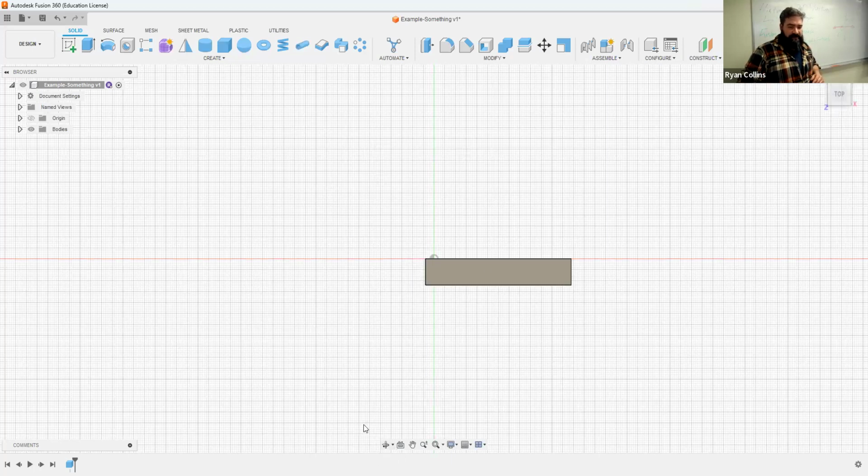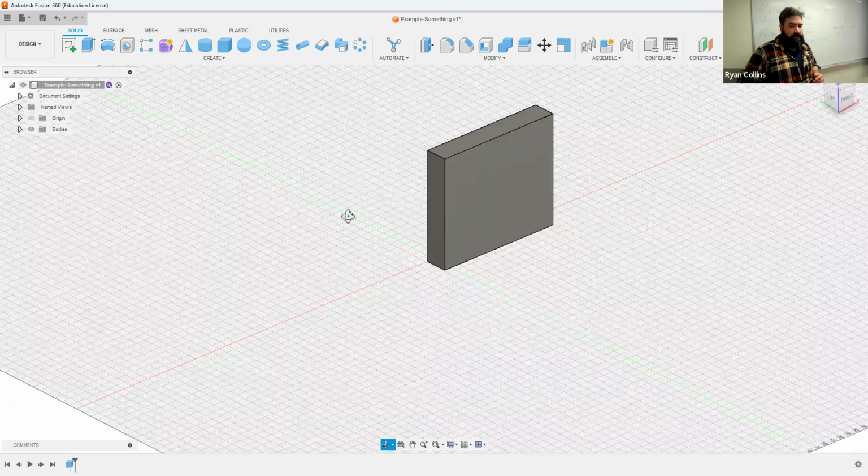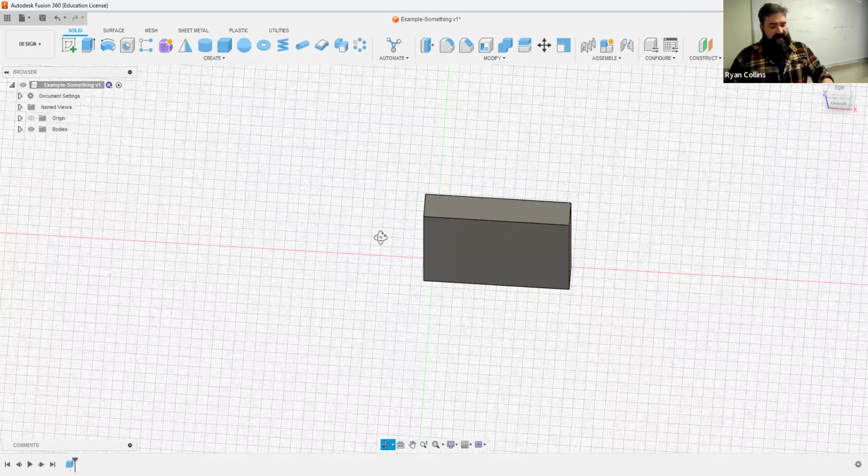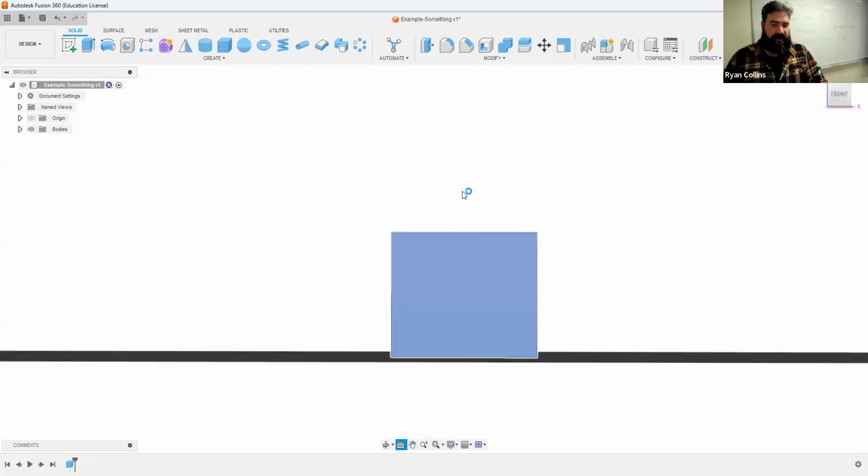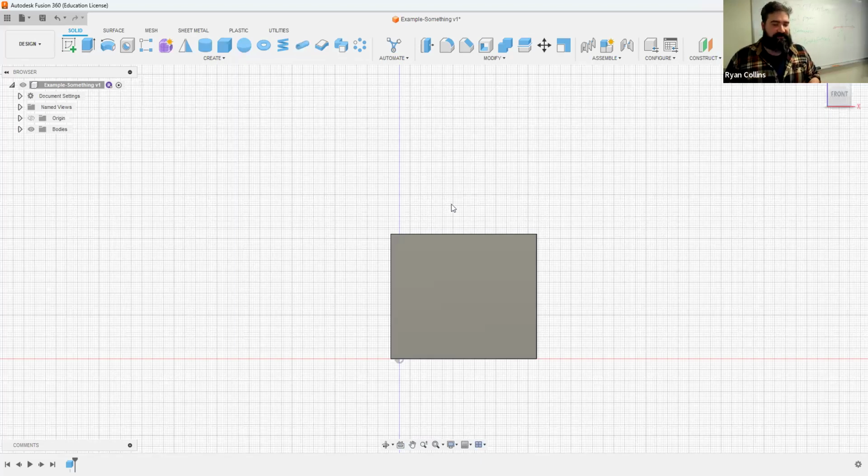Otherwise, down at the bottom of your screen, you have the click commands. So these are really there for if you don't have a mouse. So you have your orbit, click there. Now the orbit tool comes up, click and drag, and you got that. Hit escape to get out of the tool. Next one, look at, allows you to select, and it will snap to that view, to that face. If it's a rounded object or something, it'll do the best it can. Hit escape to get out.